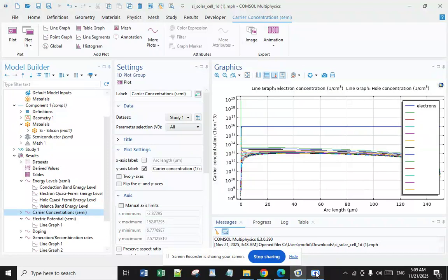And the next is back surface field, or BSF, a region of a solar cell with higher doping on its rear surface that improves efficiency by reducing the recombination of charge carriers. This higher doped layer creates an electric field at the interface with the lower doped bulk material, which repels minority carriers and prevents them from reaching the rear surface where they would be lost.